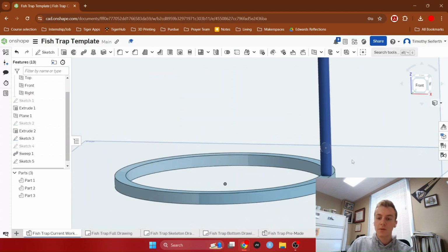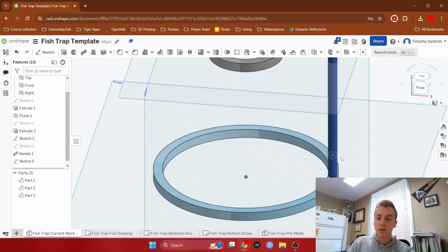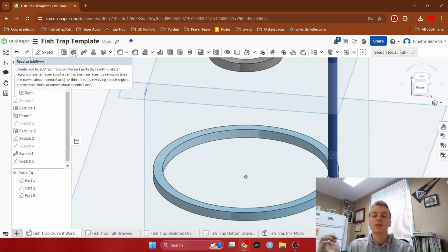And now is the fun part. We're going to make a ring using that circle with that thickness. So like I said, use the revolve function. What that's going to have us do is pick the shape we want to revolve and then pick the thing we want to revolve it around. Because we could revolve it horizontally or vertically or whatever direction we want.